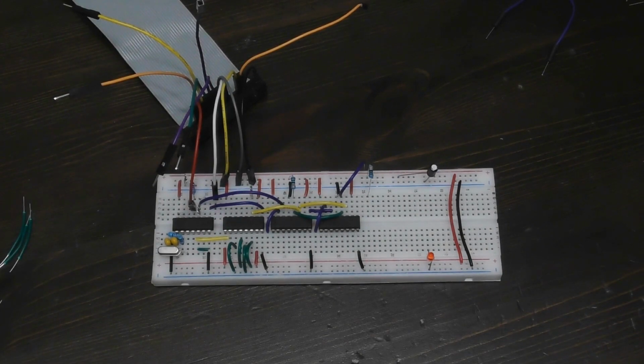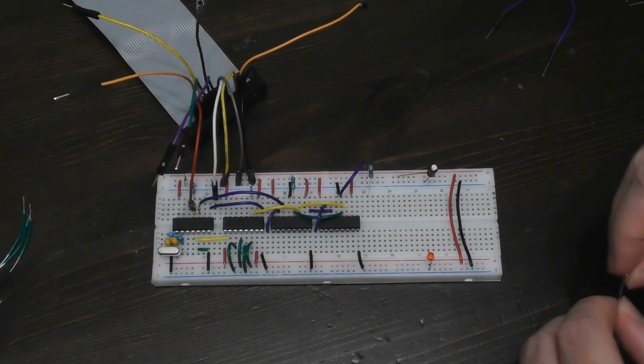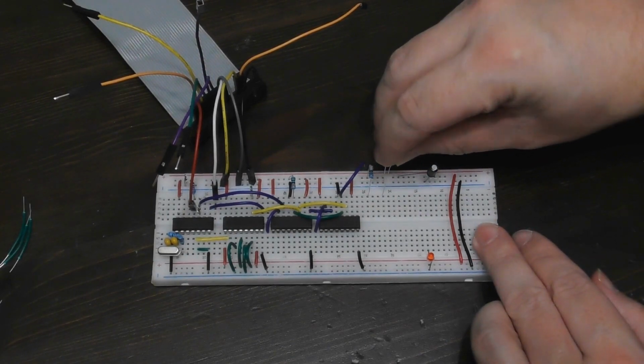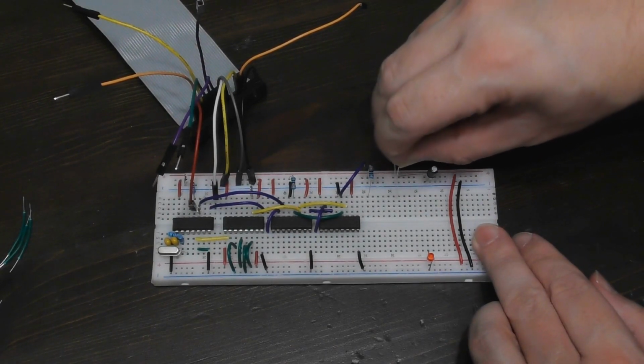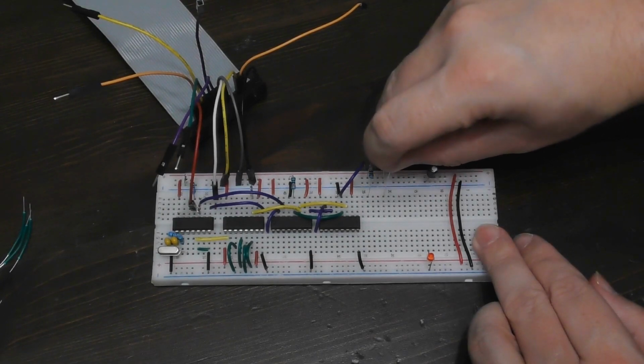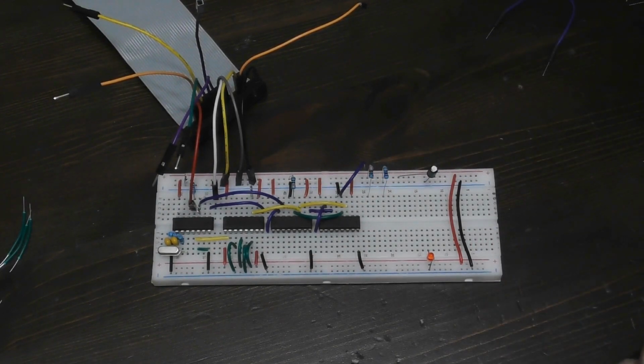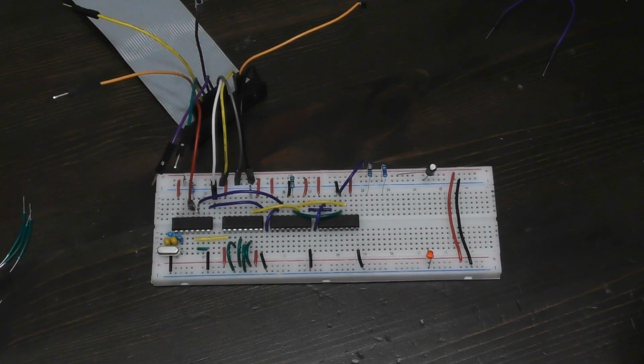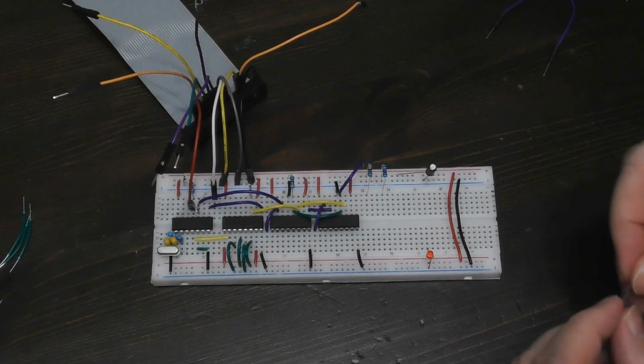Instead of doing that, I'm just going to run them all through diodes and use a resistor to pull down the signal. I'll put the resistor at the top. Let's put it a little distance away from that one. So by doing this, the resistor will normally pull the signal low, but if any one of the 4 pins that I'm sampling here happens to be high at the time, then it will pull the signal high. It doesn't matter if multiple pins are high at the same time, and the diodes will prevent them from shorting into each other as well.